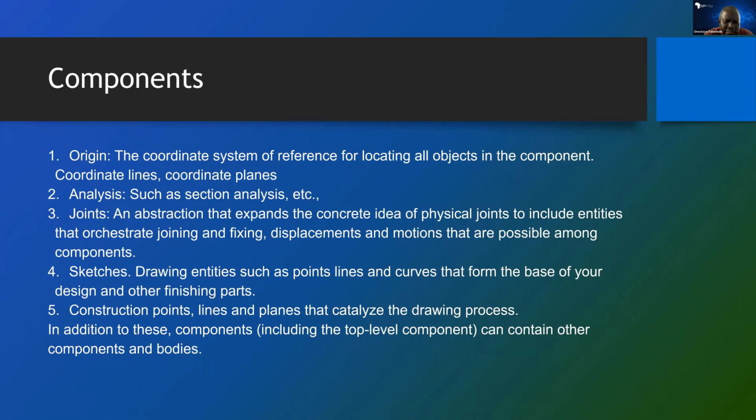And if you create a body and you do not put it inside one of your own defined components, it will remain inside the top level component. The other components you create are part and parcel of the top level component, but they can on their own contain bodies.